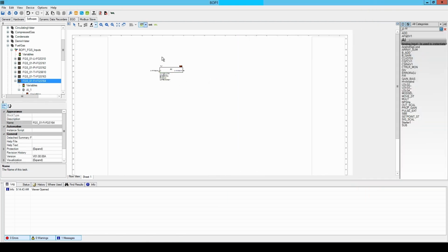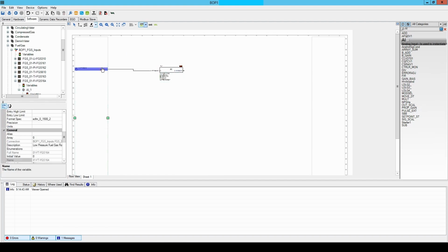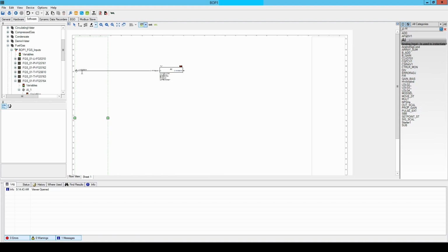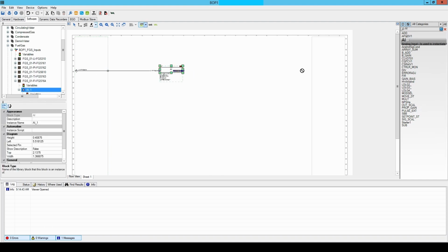Now, this will function if I download it, but I'm going to go ahead and drag it to the rail. The rails allow me to see information. They have no real function other than allow there to be a point of reference from where it's coming from. It'll also say underneath, if you set it up, it'll tell you where it's used. It'll also allow the line to change color once you download it and give you the status. If you don't have the rails, it doesn't do that.